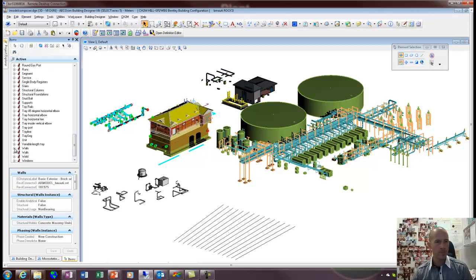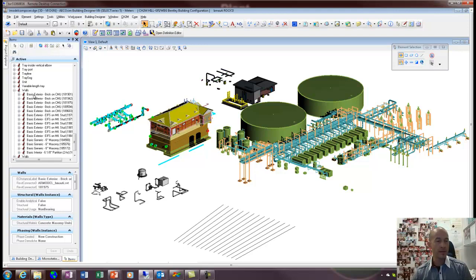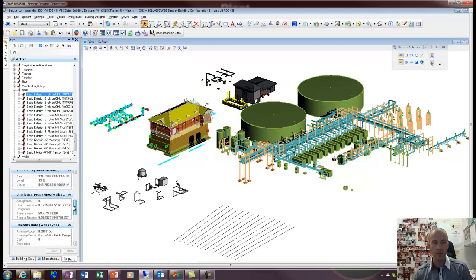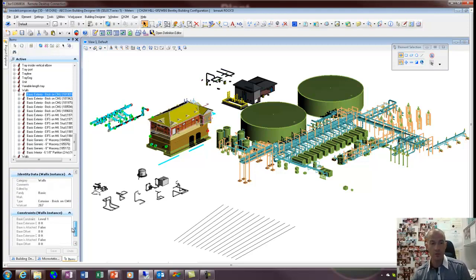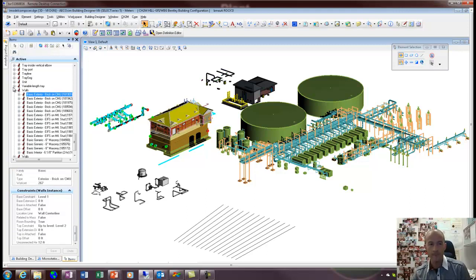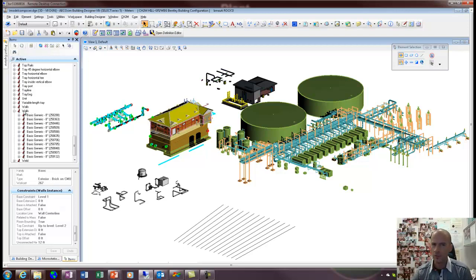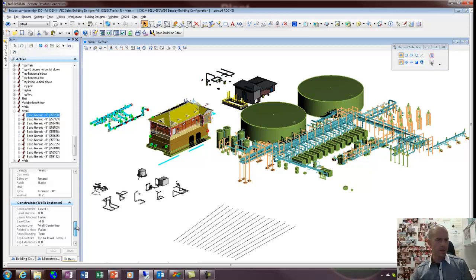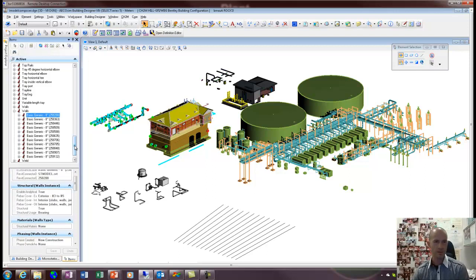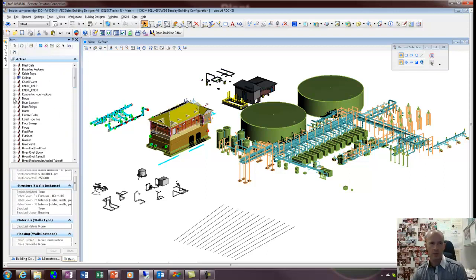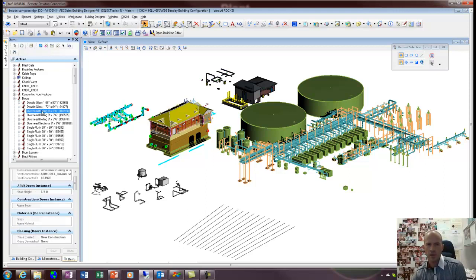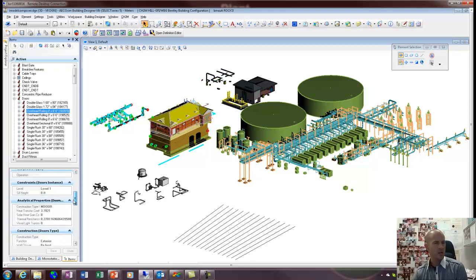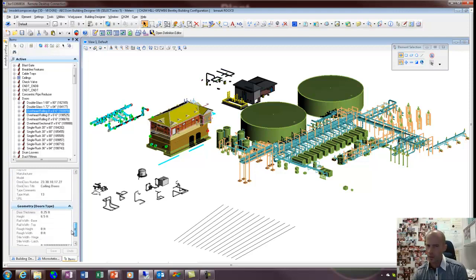Here's a simple example. I'm going to expand wall. Here's the Bentley walls. If I click on one of these walls, I'm not seeing the quantity information. I know there's areas and volumes that I can pick off, but I don't see it there. And I'm going to now select the Revit walls. Now, it's interesting that they come in a different location. They're both walls, yet they're categorized as different walls. But again, I'm not seeing everything I'd expect to see. It's very strange. Looking at doors, similar type concept. I click on the door. I know there's more stuff here, but it's not all coming through.